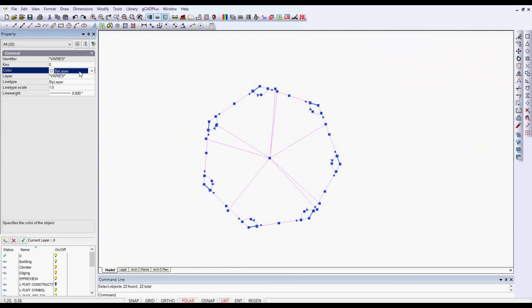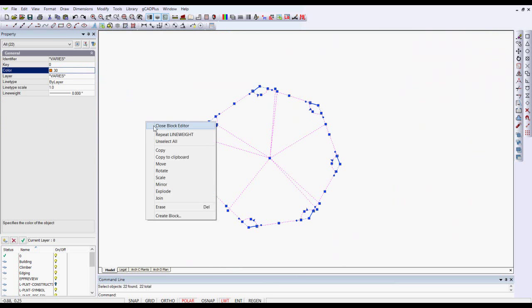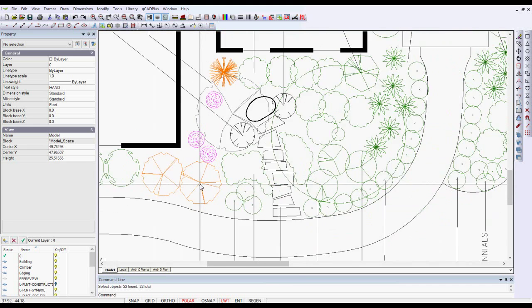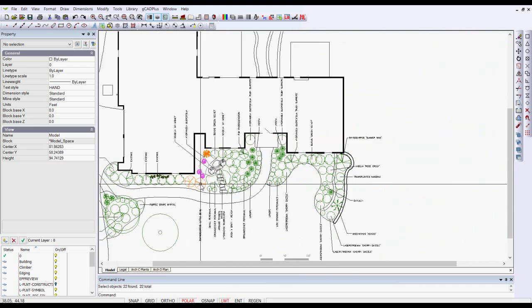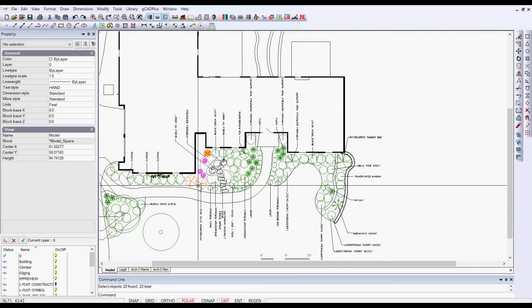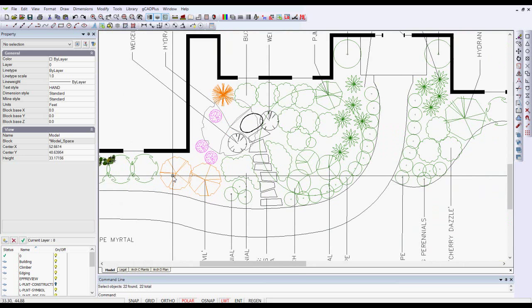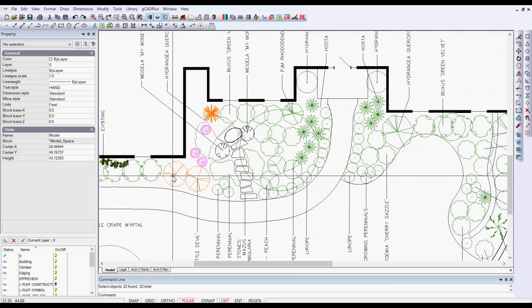We could, for the sake of argument, change from color and make color by layer now, or perhaps better still, let's make our color that bright orangey color, and we'll close. Now there's our color. And it changes everywhere that symbol has been used. So there were 2 instances of it, and 2 copies of that symbol changed.